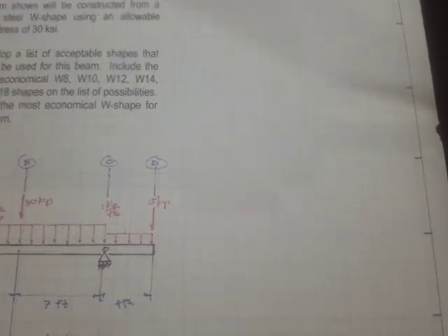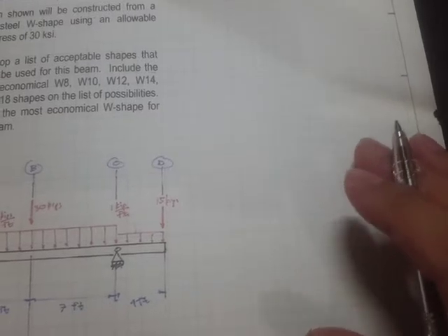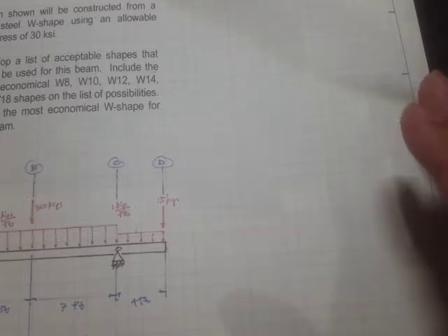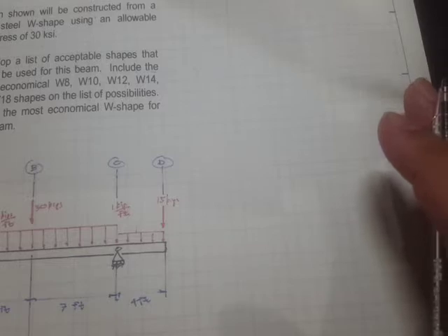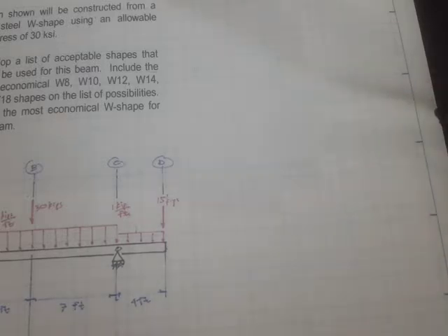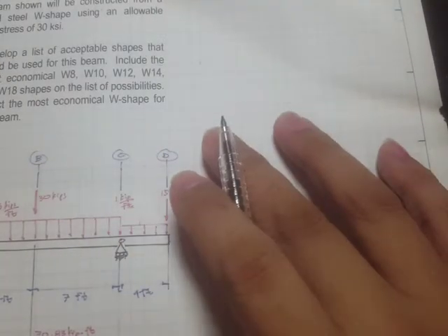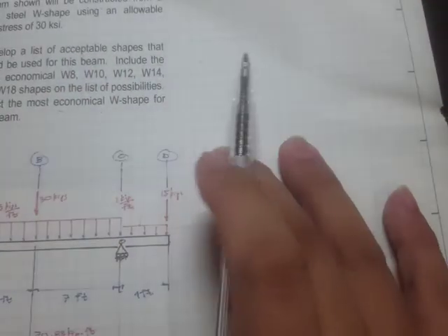If you recall, when we talked about the section modulus and the geometric properties, I showed you the tables. So there's a list of sizes of these I shapes, and we are just going to select which would be the most economical, because there are a lot of shapes that are possible for the design scenario. When you say economical, this would be in terms of the material. So we should have the least material that could do the job.